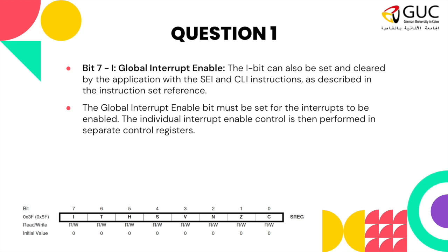I can also have interrupts regarding the environment. If I'm sensing data from the environment with a sensor, for example if I click on a button, I want to interrupt my program and perform another functionality. I can have an interrupt that detects if I click on the button or not.